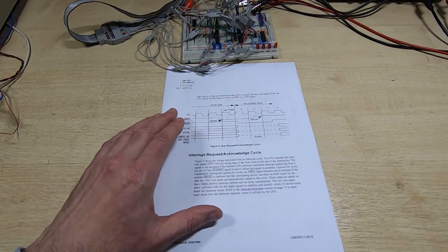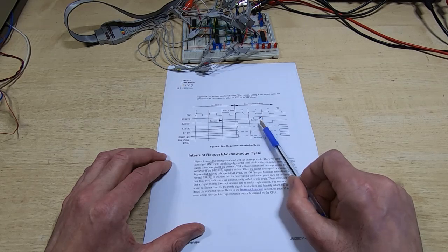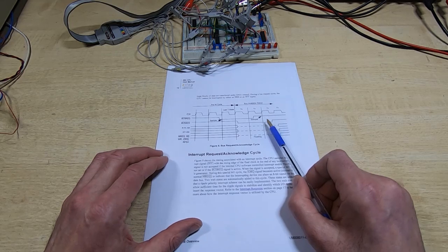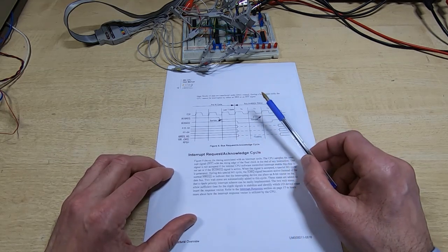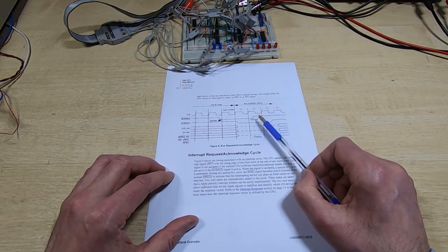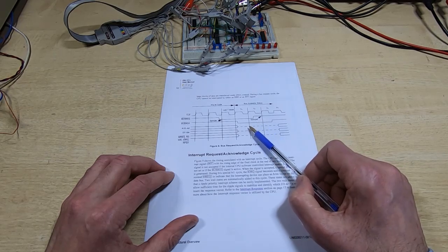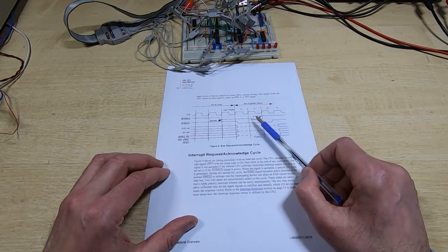Once we've got control of the data bus, address bus and control lines, that's when things start to get a little bit more complicated, because we then have to effectively take control of the system with regard to accessing RAM and our device. So we effectively have to emulate the operation of the Z80.